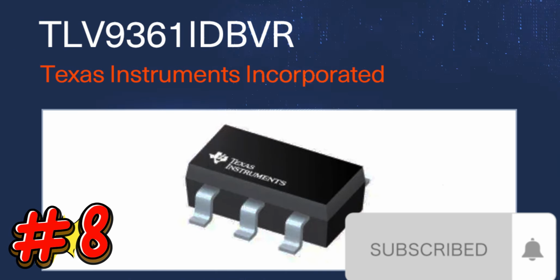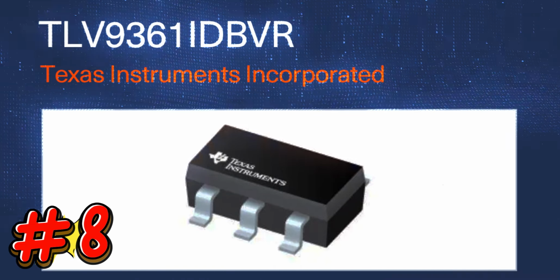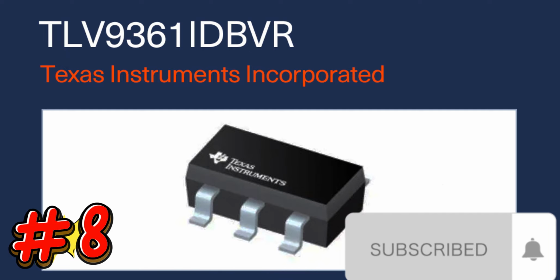The TLV9361IDBVR also features high output current of plus or minus 60 milliamps and a high slew rate of 25 volts per microsecond.